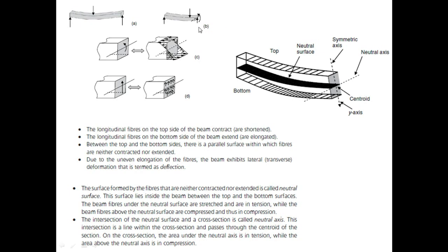Okay, so after cutting. Now, in figure C, because of this bending moment, the bending stresses have been generated. These are the bending stresses. You can assume that basically these bending stresses might be showing compression over here and tension over here, and as a result of this shear force V acting on this plane, it has created a lot of shear forces along this area A, thus resulting in what is called the shear stresses. And because of this bending moment, the bending stresses have been generated.